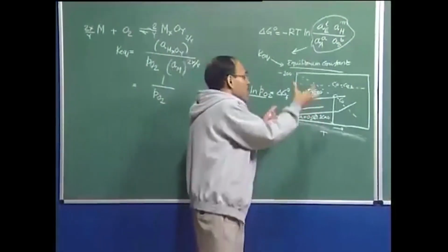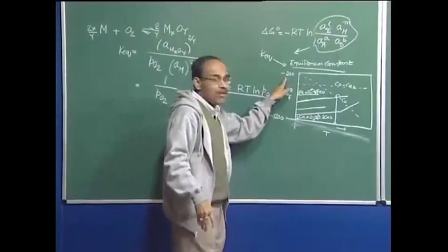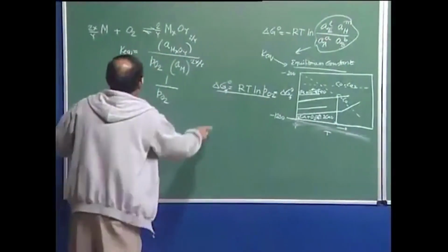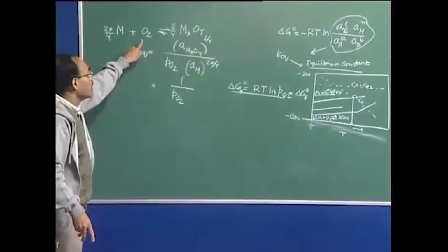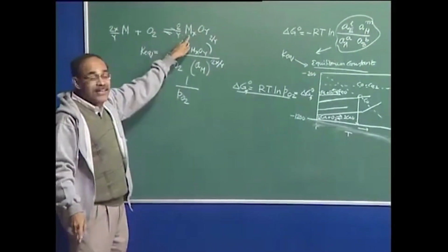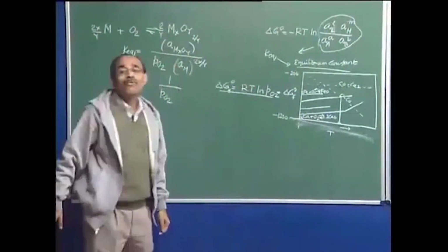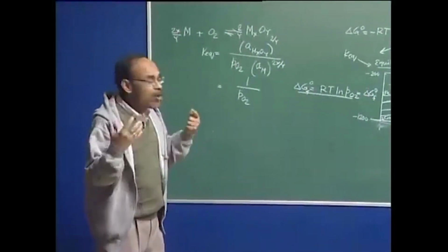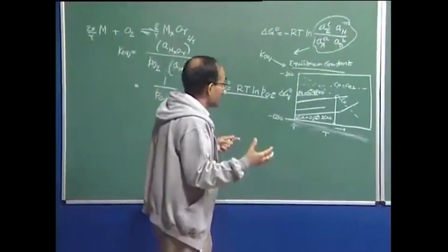Similarly, we have sulfide diagrams also. Per mole of sulfide, we can find out the standard free energy change, where we take a metal, take sulfur gas, and form metal sulfide, and exactly the same sort of graph can be produced. This is known as the sulfide Ellingham diagram, which gives us an important clue regarding pyrometallurgical or sulfide smelting processes.